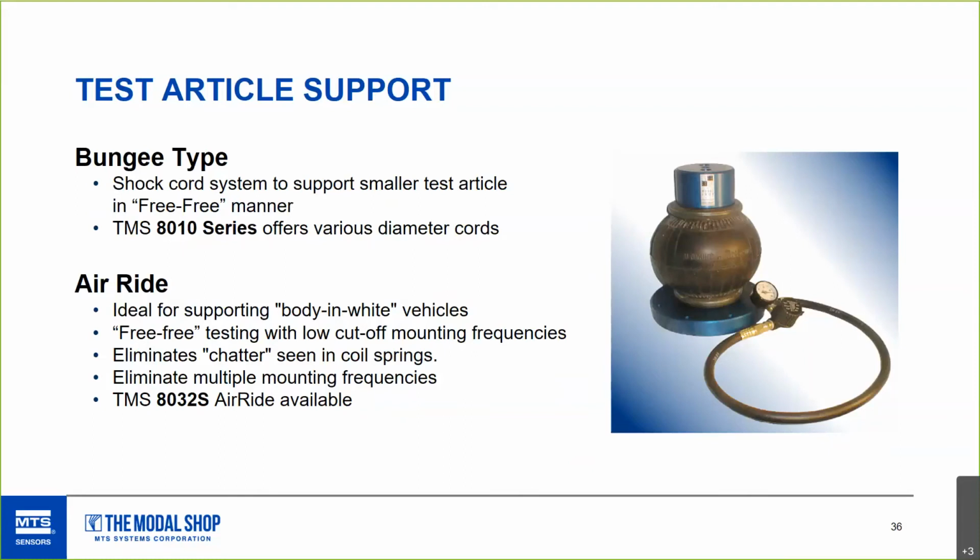But you might also be testing in a loaded condition, as it were. You might be testing some item that's always going to be used with a certain payload on it, and you want to actually have that load on it that it experiences in reality and test it with that. So it might not be a free boundary condition, but more of an in situ kind of test. So there are a number of ways you can support it. We've got a few tools that can certainly make life easier for that free approximation. But also keep in mind during your test setup what is appropriate for what you're trying to learn during your test.